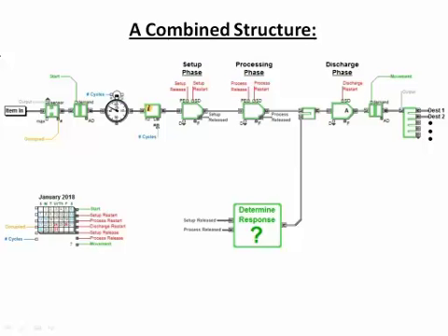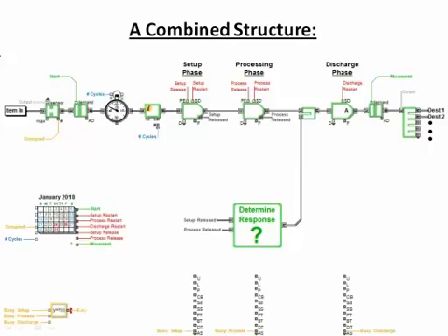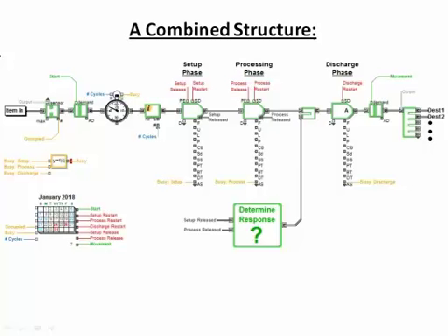Because some of our repair times and some of our processes can only happen when the block is occupied, we look at the pound-signed output of the first gate to see how many items are currently in process and feed that into our calendar block. We use the activity status signal and parse it to determine the busy signal, which can be used both for our number of cycles operations or as a where connector input.